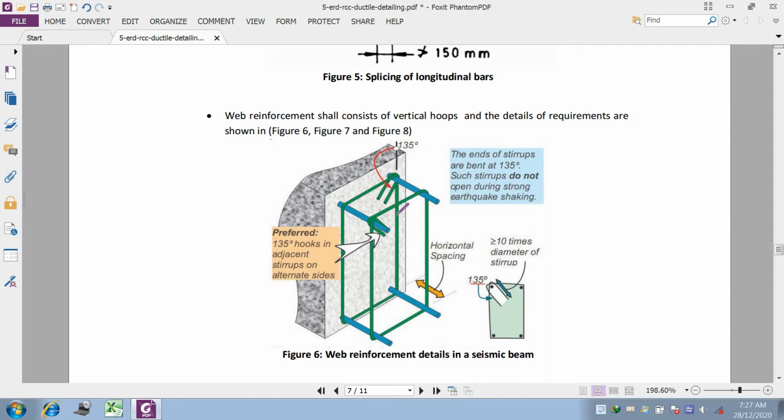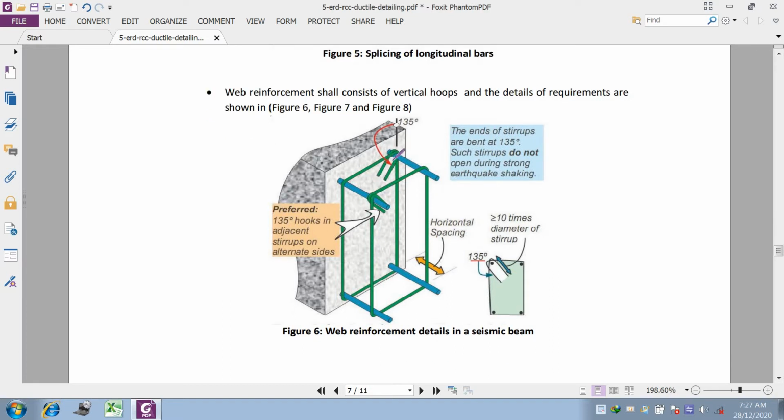During construction itself, many times the workers are not able to bend these stirrups. They just do their usual work and bend the stirrups at 90 degrees or 60 degrees. The anchorage of these stirrups is very important as far as earthquake force is concerned, because during an earthquake the shaking directly transfers the force to structural members like beams and columns.